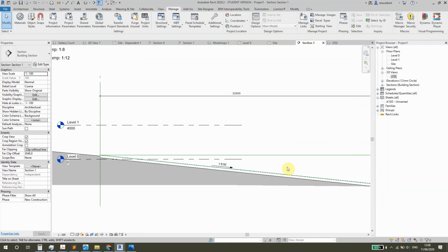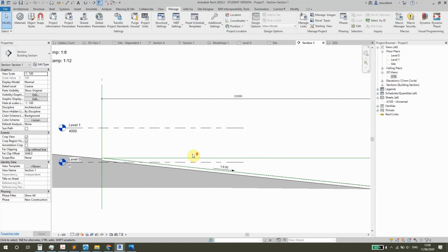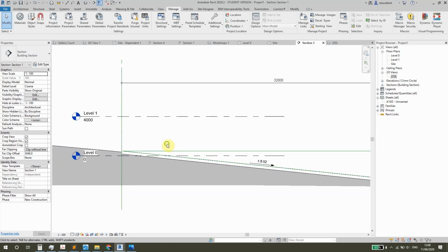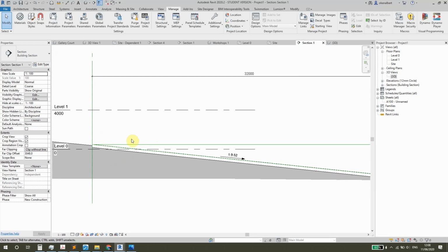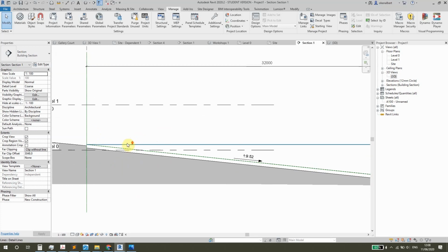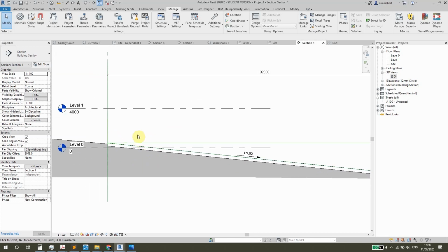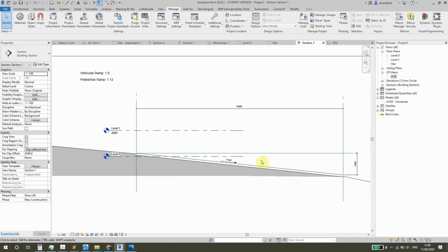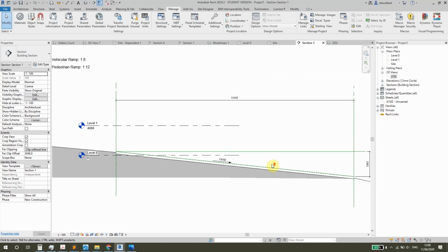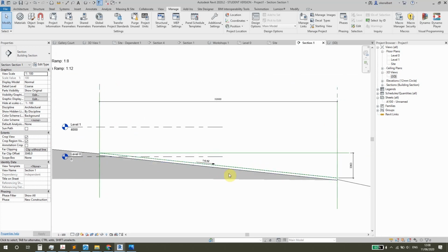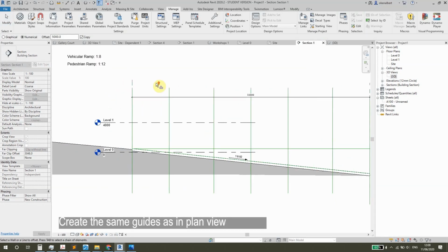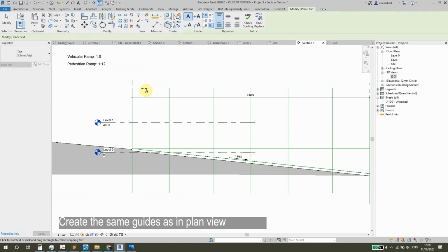If you are a cruel architect, you would leave it at that. But this is still quite steep for people to walk on, assuming that a vehicle is parked here and by mistake the handbrake is not pulled all the way, vehicles would start rolling down the hill. So making a much gentler slope would be a good solution. But the problem is we have a sloping site. Let me just offset this 5 meters.